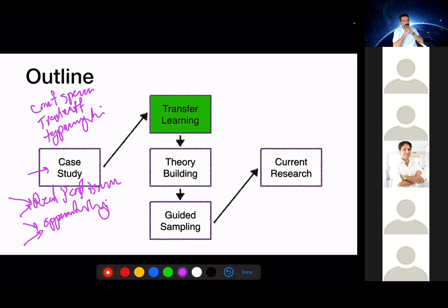So you don't want to access the memory a lot, and you could have the same latency for your inference, but considerably different energy consumption for the same task, right? It depends on your architecture, on the way you consider accessing the memory and what type of memory, right? This makes a massive difference in terms of energy consumption, and this matters a lot.